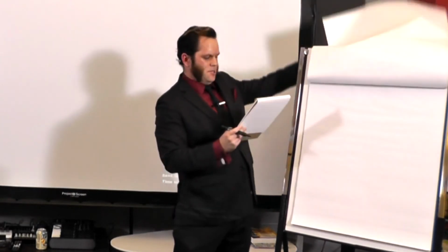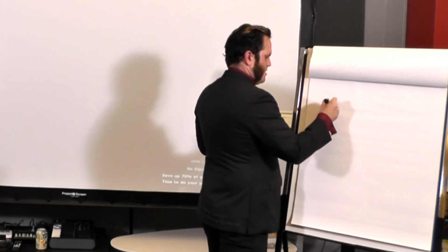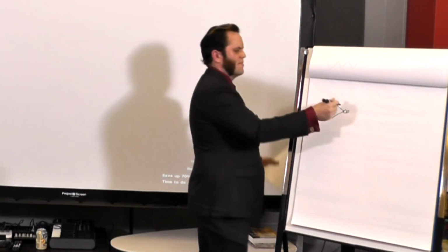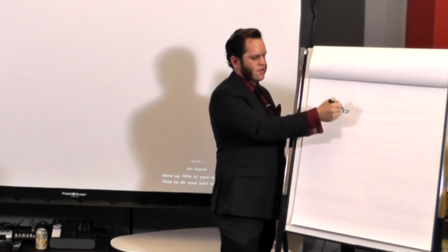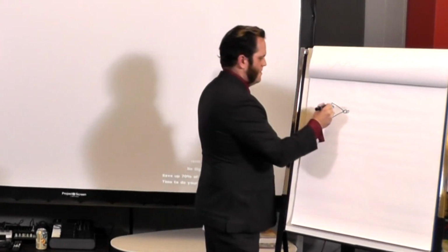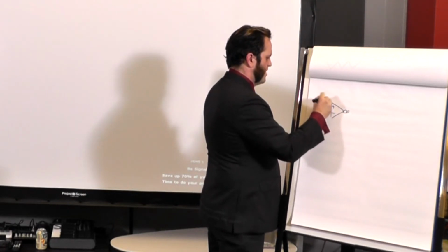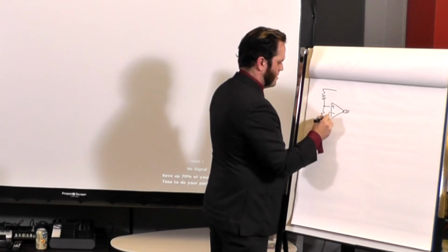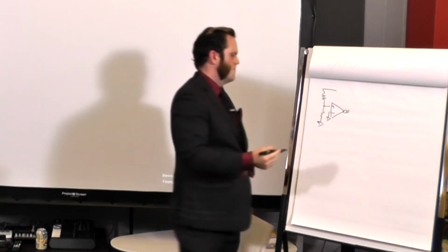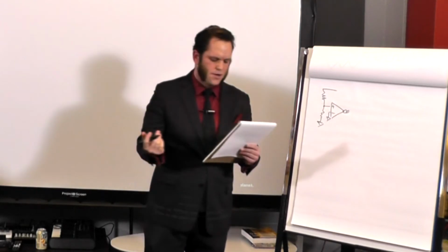And a lot of that's essentially the same as what we just looked at, except we're going to do some little trickiness. We're going to take an OTA up front. By the way, I forgot to talk about this. This is the magic that tells you it's an OTA, this little current source in the front of the triangle. That's how you know it's not an op amp and you can't wire it up the same way. And I'll just throw something out here, a little unlabeled resistor divider, because we like unlabeled resistor dividers, and that's just going to go to ground.